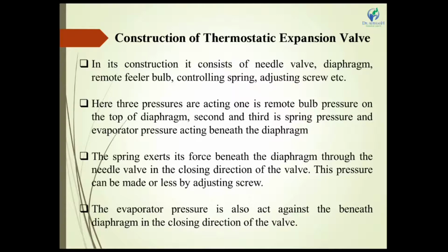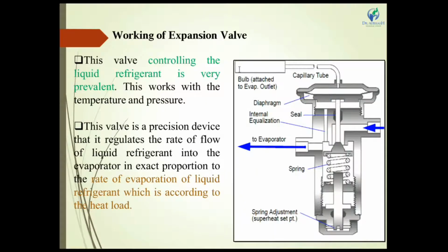The evaporator pressure also acts against the diaphragm in the closing direction of the valve. In the same way, if the temperature goes down, the diaphragm moves in an upward direction. We have to study the working of the expansion valve.